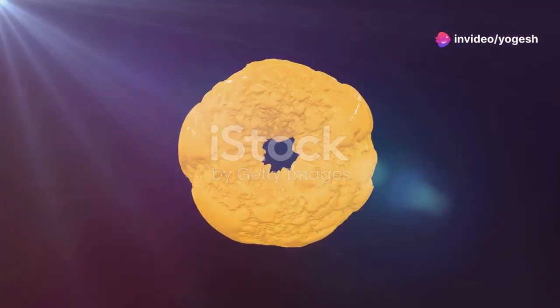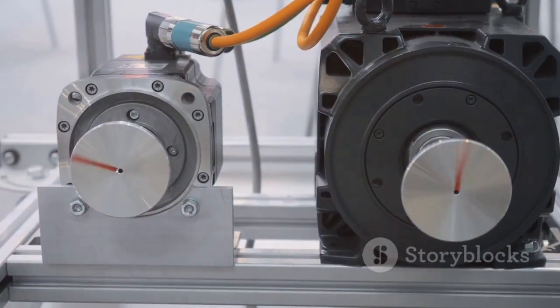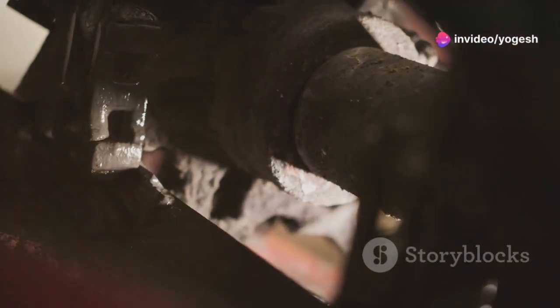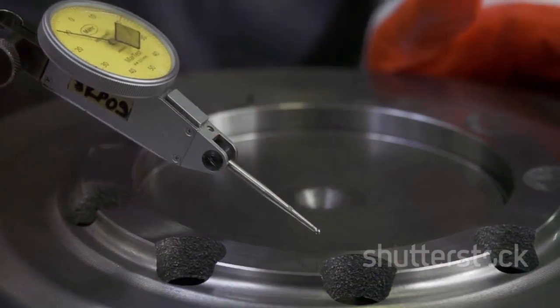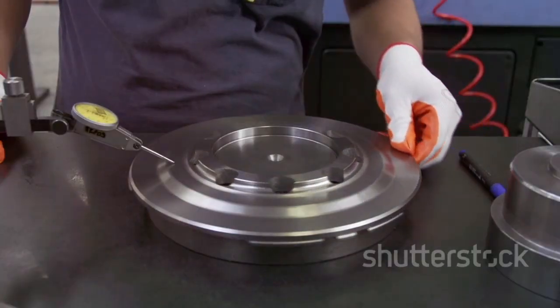Imagine a donut with an off-center hole. That's poor concentricity. In engineering, we want the centers of circles or cylinders to line up exactly. For example, a shaft fitting into a hole. Both axes must align for smooth operation. Even a tiny misalignment can cause big problems, so we set limits on how much off-center is allowed.